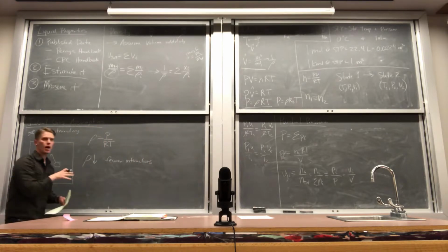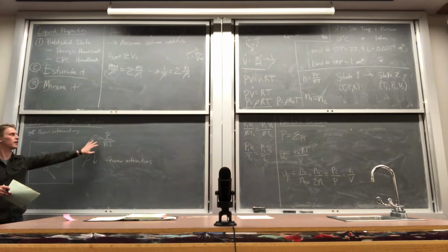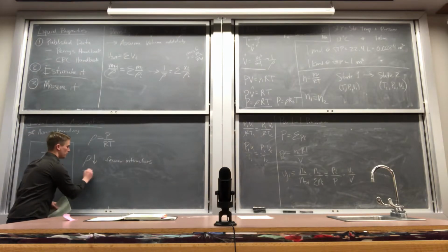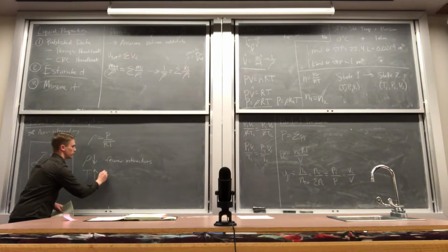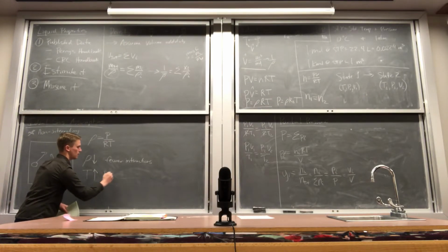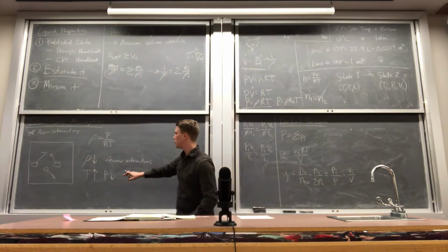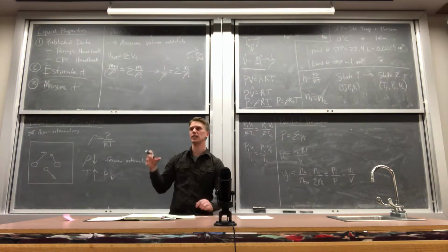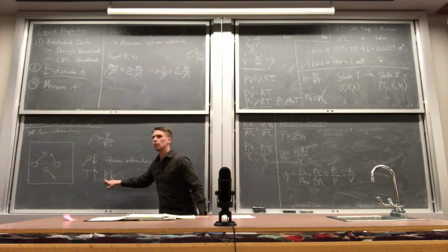So how can we accomplish a low density fluid looking at the ideal gas law and the relationship between pressure, density, temperature? High temperature. So this is accomplished when temperature is high or when pressure is low. So every single equation of state should reduce to this sort of behavior. Everything should become an ideal gas when you have either a high temperature or a low pressure.